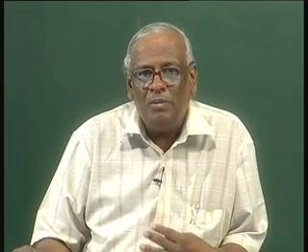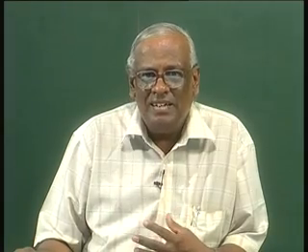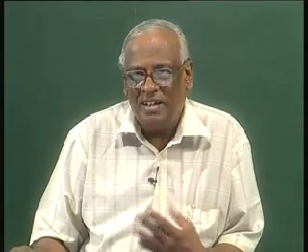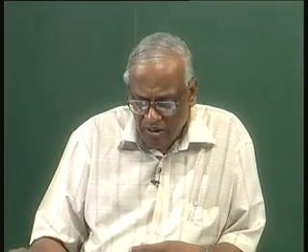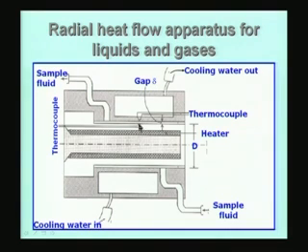So, the gap here is full of air, and the thermal conductivity of air has been measured by various people, and very accurate values are available from the literature, from the tables given in many books on heat transfer. You can find out the thermal conductivity of air very accurately. So, all I have to do is give different amounts of heat into the heater and find out the temperature difference across the gap. We also know the thermal conductivity of air at that particular mean temperature. So, you measure the mean temperature between the two, and we know the thermal conductivity of the air at that temperature, and therefore, I can find out how much heat is transferred from the inside to the outside by conduction through air. Okay.